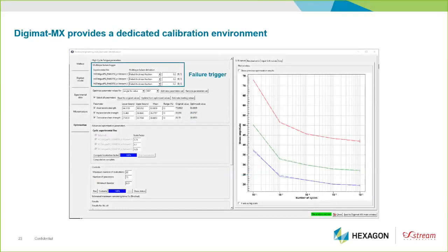So it can cover failed thickness fraction, average over the thickness, first ply failure, etc., exactly as we are used to for static failure. It provides a lifetime target selection, where we can focus on a specific lifetime for the calibration and then propagate, as you will see, or have more of an overview in terms of optimization of the failure indicator.